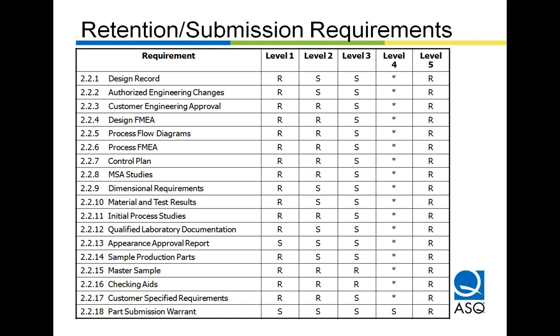It says in Section 1 that the organization shall obtain approval of their PPAP for a new part or product, for a correction of a discrepancy on a previously submitted part, for a product modified by an engineering change to the design record, specifications, or materials, or any situation that's required by Section 3, and Section 3 goes into other specific examples.